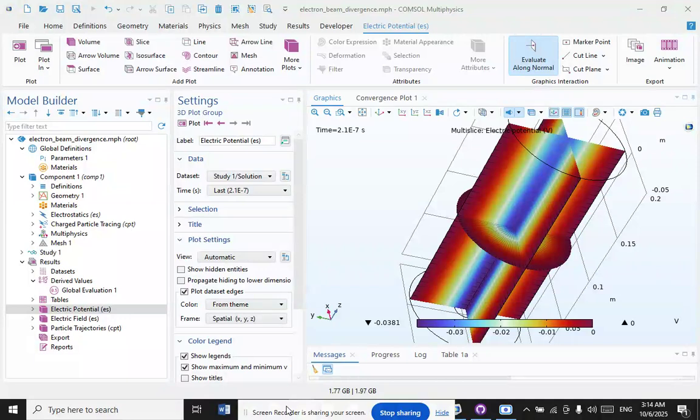With sufficient power density, a thermocapillary or keyhole is generated through the substrate as the material is vaporized, allowing the beam of electrons to penetrate further into the substrate. This thermocapillary generation is the mechanism by which this process has such high productivity, as very thick sections may be joined in a single application of the beam.